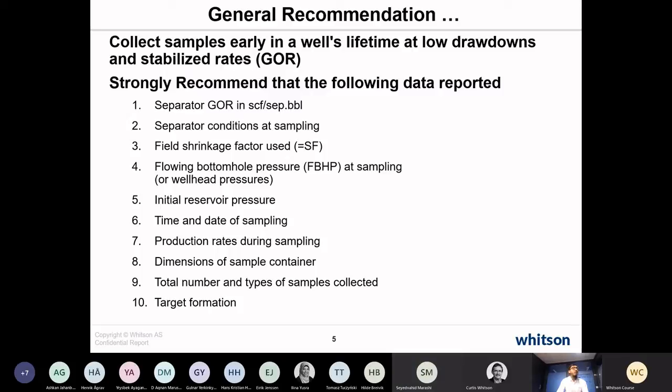So in that case, if you want to develop a very robust PVT model that describes all the compositions and all the PVT data accurately, we need a lot of samples, and we need PVT measurements on all those different compositions, so that we cover the entire composition, pressure, and temperature space for our PVT model development.